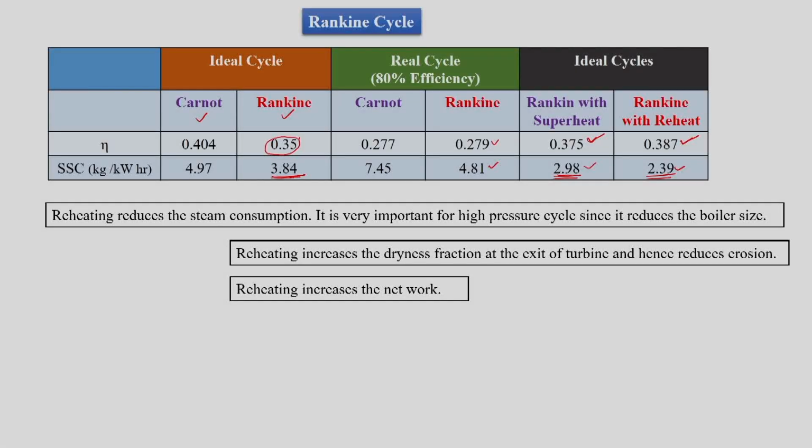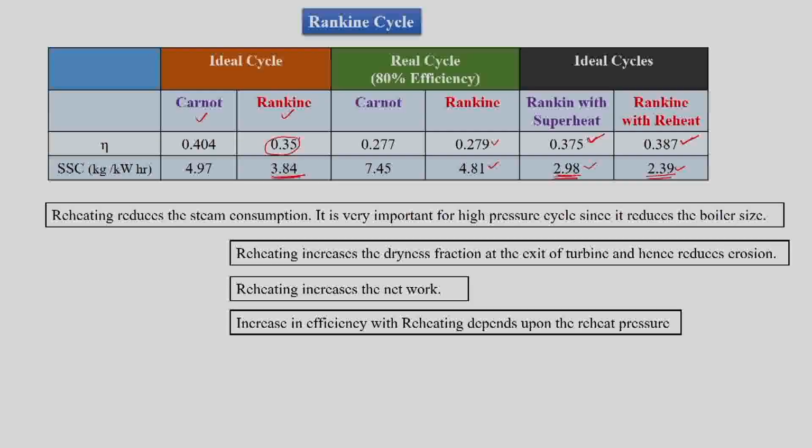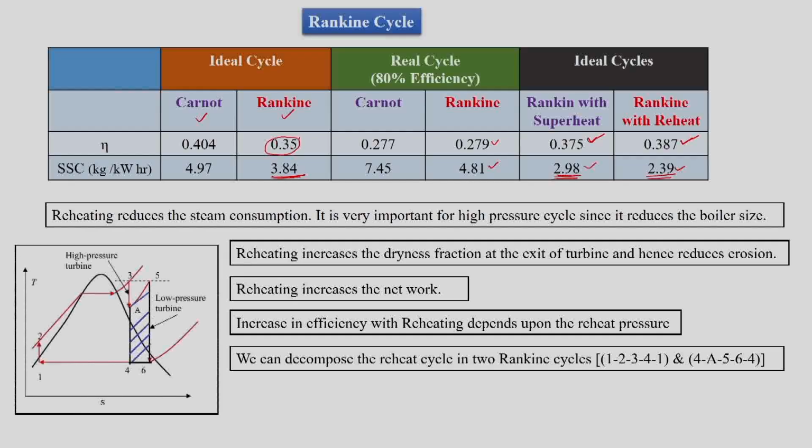Reheating increases the net work, since turbine work increases. Then we have an increase in efficiency with reheat, as we can see over here, but it is not always possible that we will have an increase in efficiency with reheat. We can see when we can have an increase in efficiency.